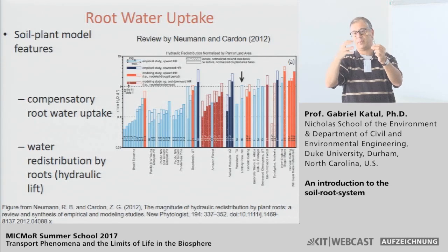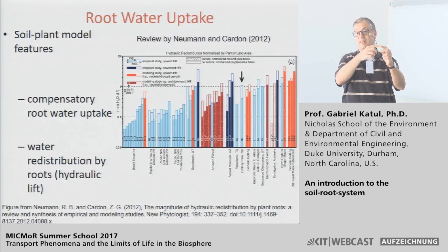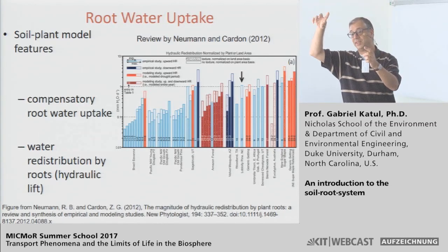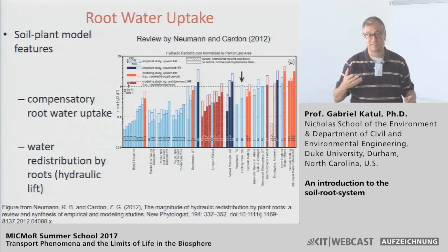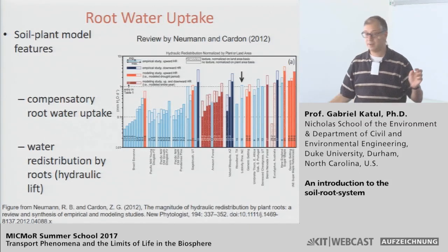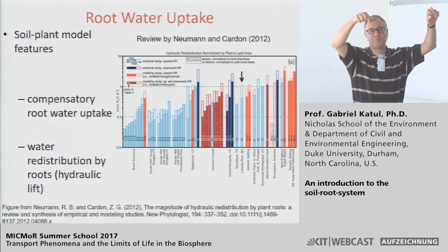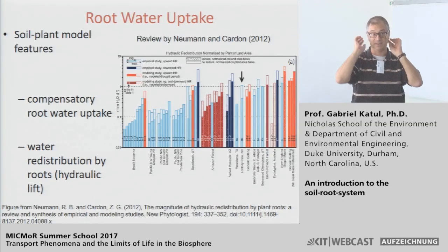Water can go from the wet soil to the roots, but if the roots cannot store much water, then that water will have to come out from the rooting zone into the dry levels. And that is basically a hydraulic lift phenomenon. But the opposite can be true. You could start with a very wet soil and push water down into the rooting zone in a 1D framework.